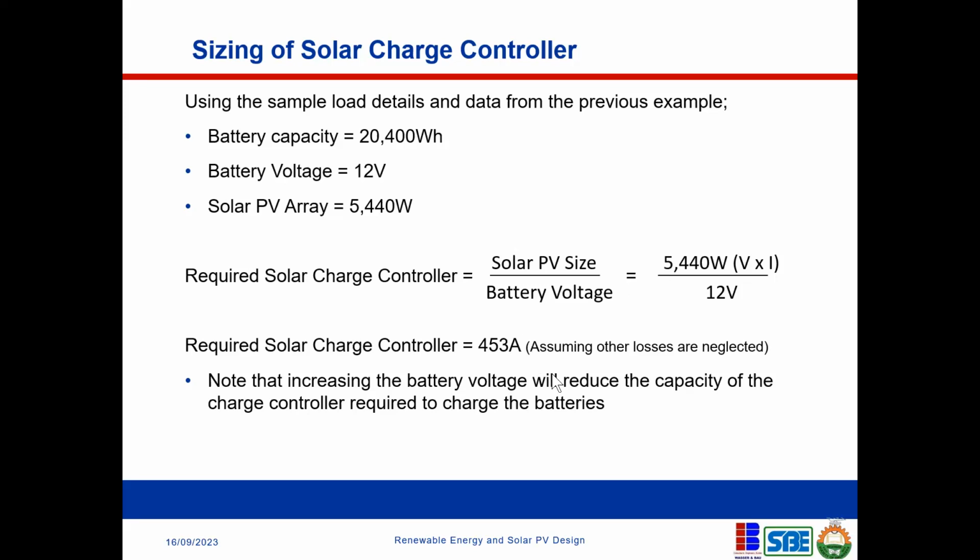I will come in here, please. I'm an electrical engineer and I've done electrical services design. So there is actually a chart. Even if you want to use Nocaco, for example, Nocaco cable will give you their chart. They will tell you this size of cable, 25 mm square, will take maximum this rating. So there is a chart from electrical background, point of view.